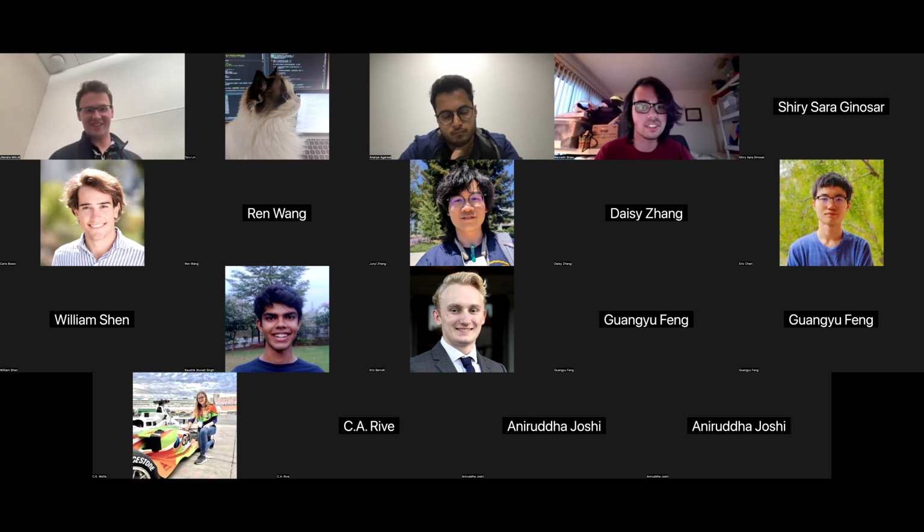Hi, it's me again. I wanted to push more on this. You mentioned tactile sensing and haptics. I wanted to get your thoughts on the state of tactile sensing for hands and robotics, and also haptic teleop interfaces. Yeah, I think for tactile itself, GelSight has been very common on grippers or on Allegro Hand or LEAP Hand V1.